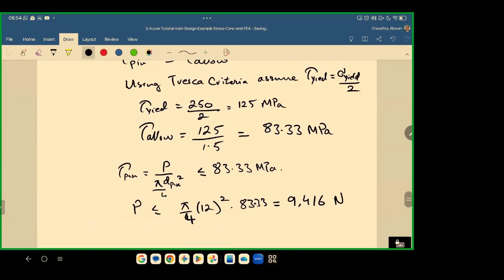This one? So this is what I explained to you. We do not have, in the question, the shear yield given, right? We also did not have the normal yield given, right? So for the normal yield, what did we do? We went to the database. In the database, we had the property of the normal yield for A36. Now we have two options, unless we search more and find from somewhere the actual value of shear yield for A36, which I told you will not normally be available in the databases.